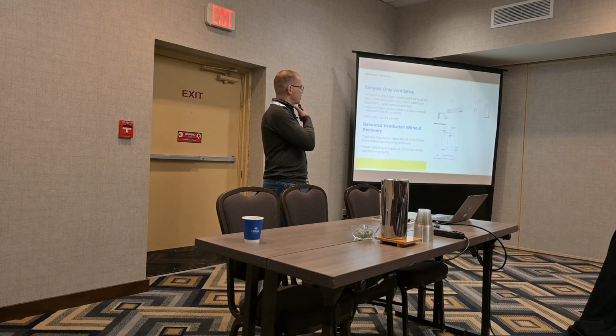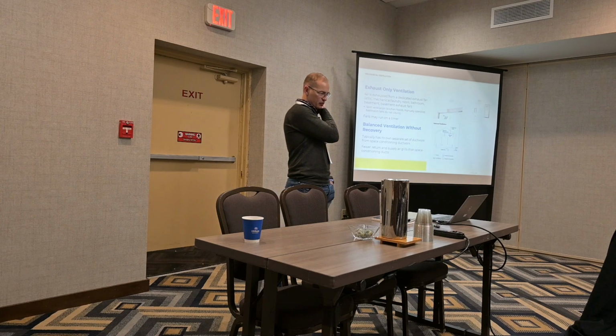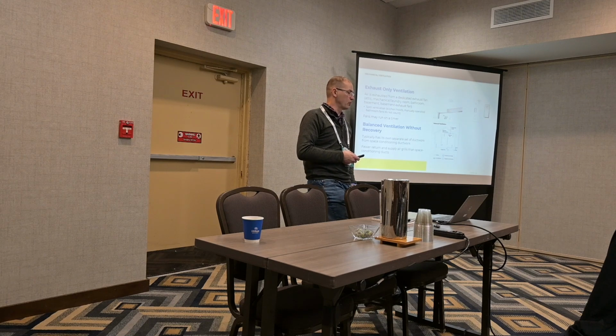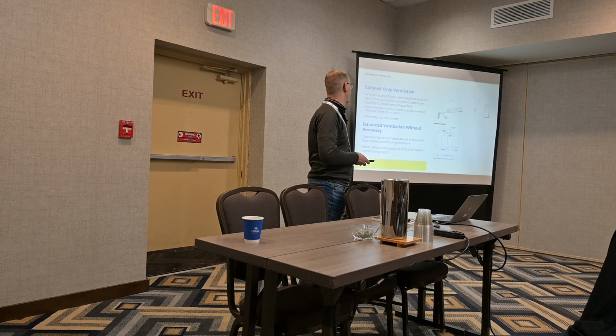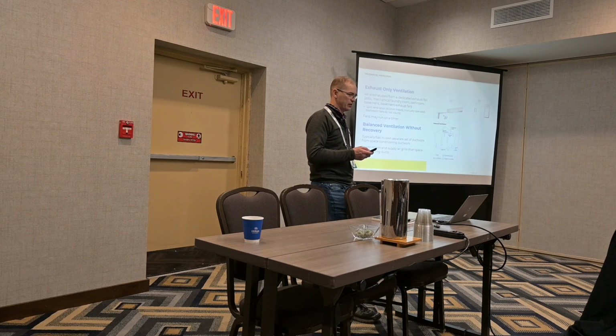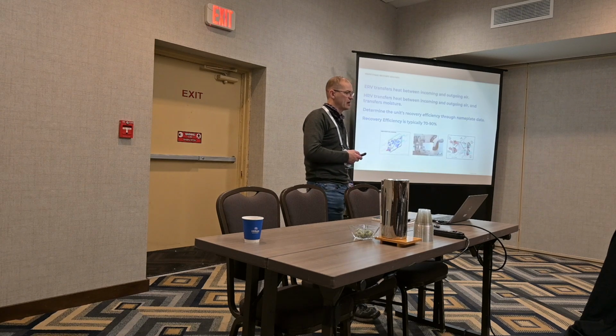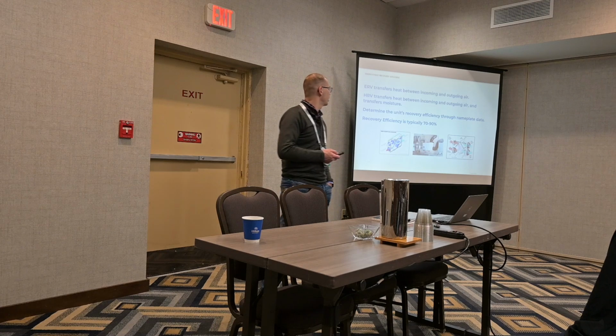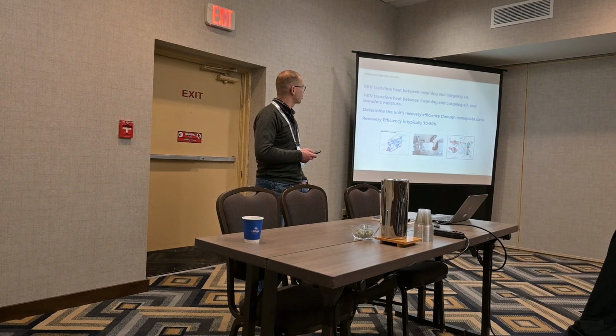Exhaust only ventilation is one type of ventilation where you just pull air through the house. Balanced ventilation without recovery both supplies and pulls air from the house with returns and supply grills. And then the air can be conditioned through an ERV or an HRV.